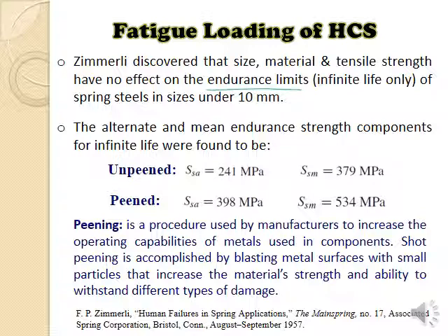So the endurance strength, and if we consider infinite life, meaning N is greater than 10 raised to the power 6 cycles. Then one of the researchers, Zimmerli, has found that the size, the material, and tensile strength have no effect on the endurance limit Se if the wire is less than 10 millimeter diameter.